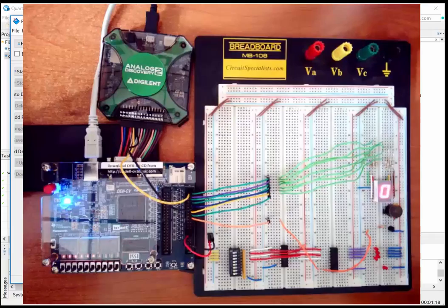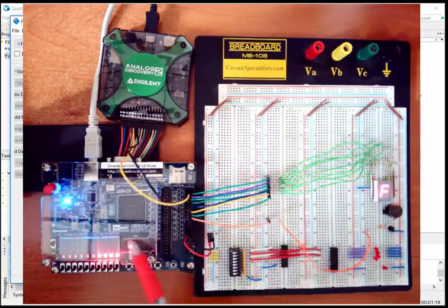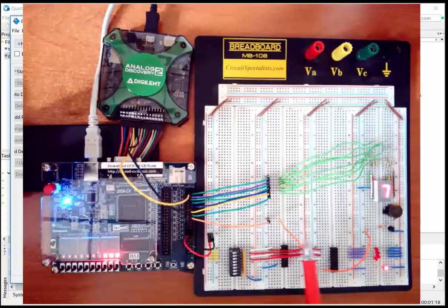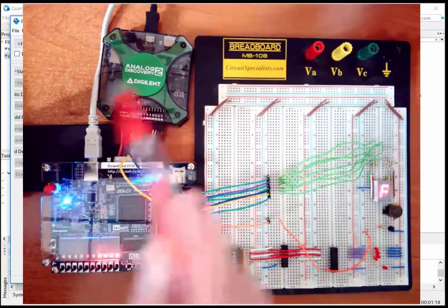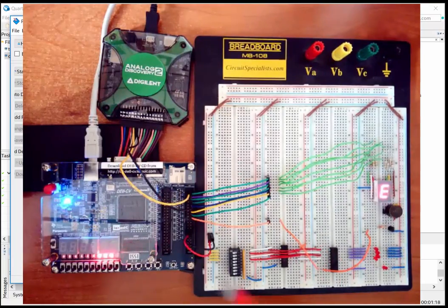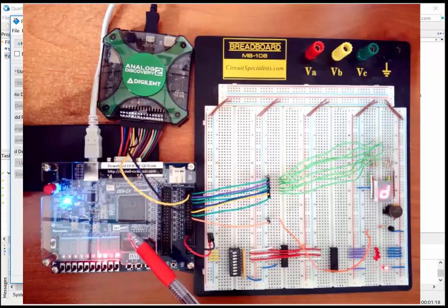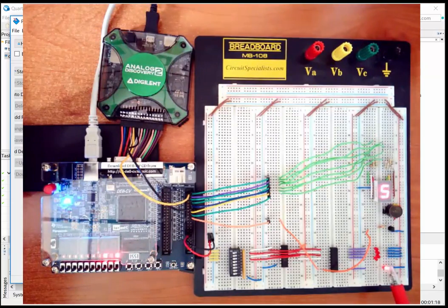Chapter 3 was interfacing. Well, there is no better example of interfacing. We have a ground shared across these 3, and we're sending a 3.3 volt logic level back and forth between these systems, and it's being interpreted. Chapter 4 was combinational logic. We have a prime number detector in here, which is a combinational logic circuit that looks at 4 inputs and produces a single output.